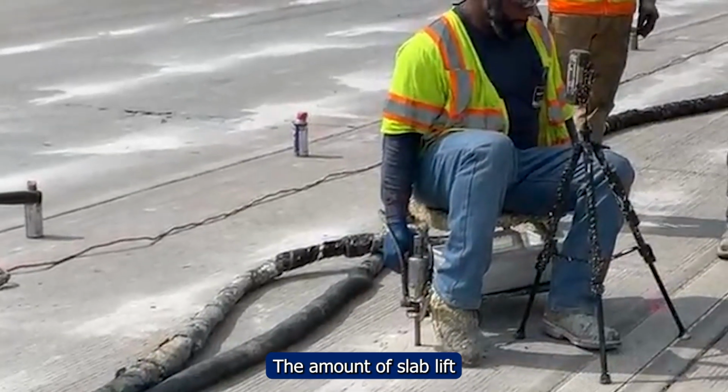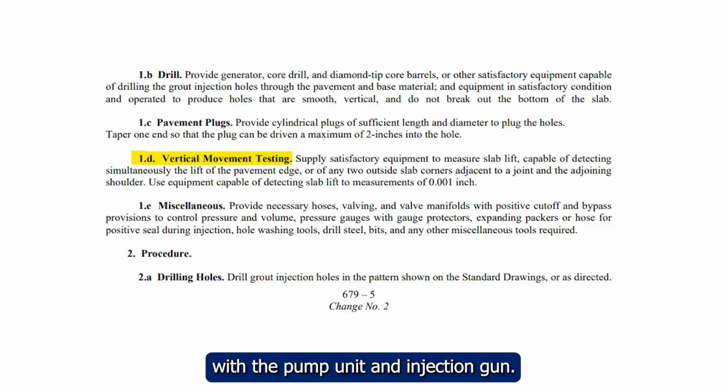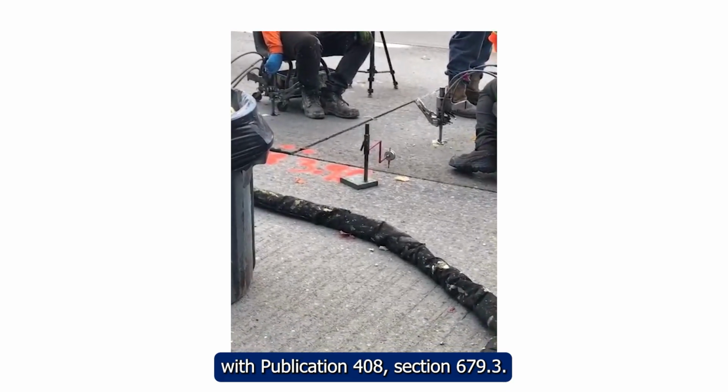The amount of slab lift must be carefully controlled by regulating the injection rate with the pump unit and injection gun. Slab movement, meaning vertical movement testing, must be monitored in accordance with Publication 408, Section 679.3.